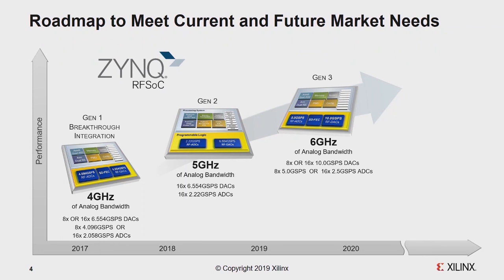It is a monolithic device. It integrates, on the same chip that's dissipating quite a bit of digital switching noise, these very sensitive RF sampling data converters, where the noise spectral density of the device is in the minus 150 to minus 155 dBm per root hertz. So very comparable to any tier 1 RF sampling data converter. And it's quite an effort to maintain the isolation. But that part's out, and it's very successful. So we went ahead and announced Gen 2 and Gen 3. These were both announced in February of this year at Mobile World Congress.